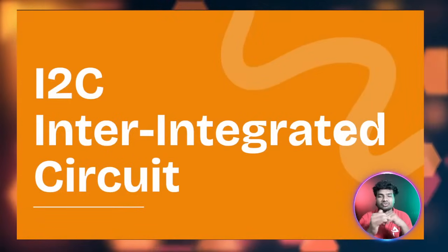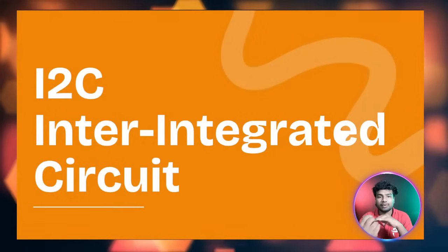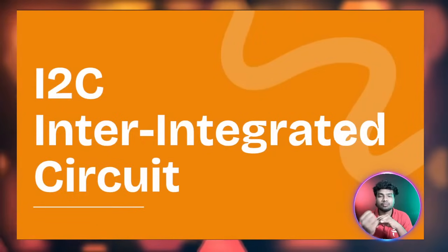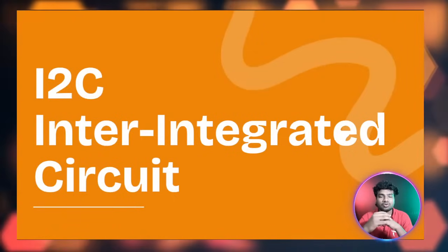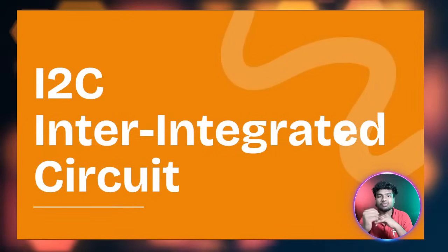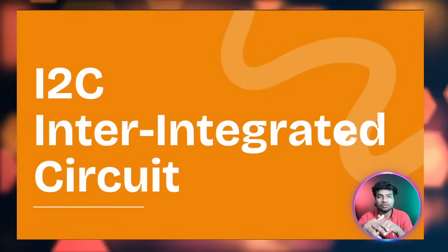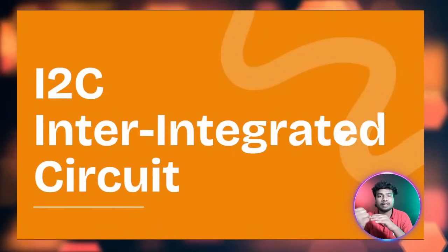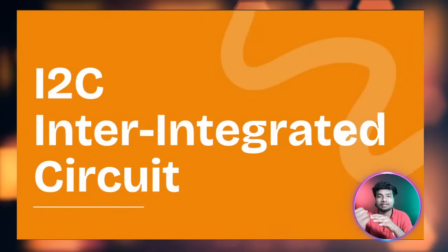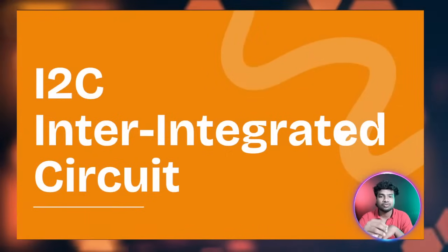Firstly the master will initiate the process by pulling down the line. If you have multi-master multi-slave, there is a process of arbitration. The master that wants to communicate with the slave firstly pulls down the SDA data line, and then only that master will get access to the I2C bus.